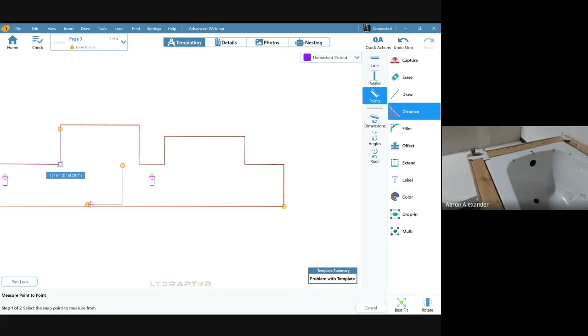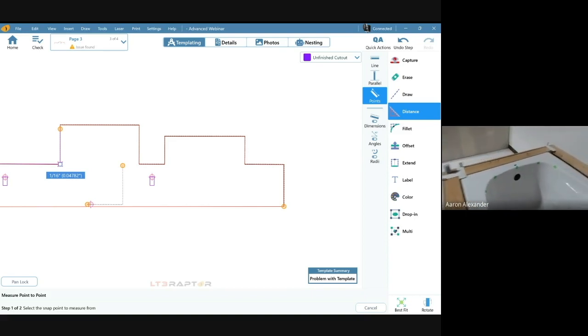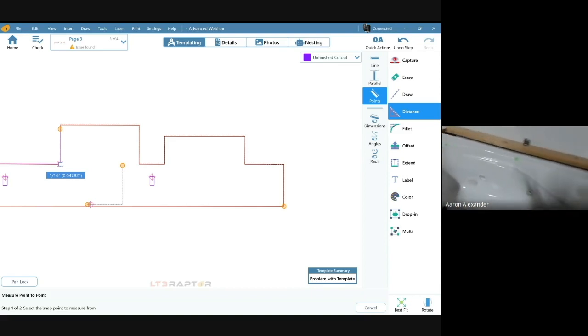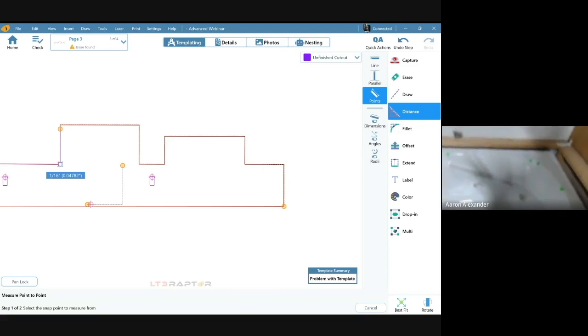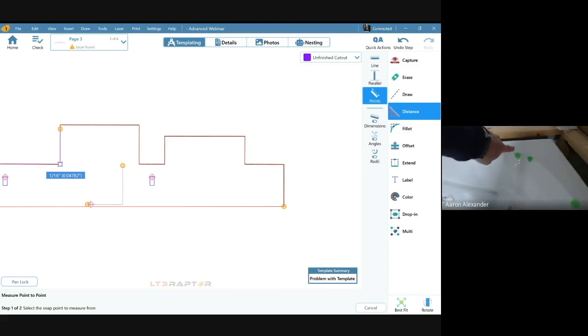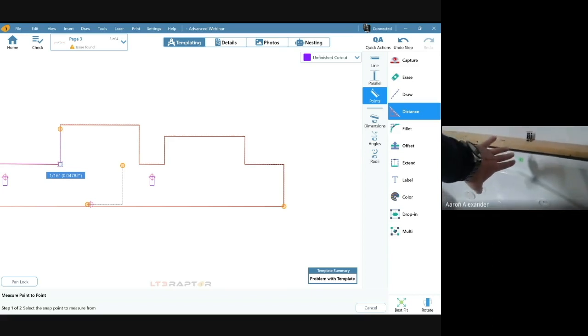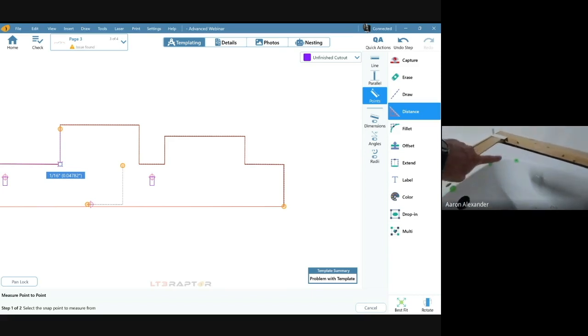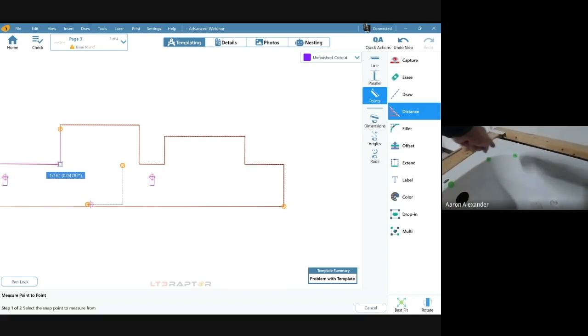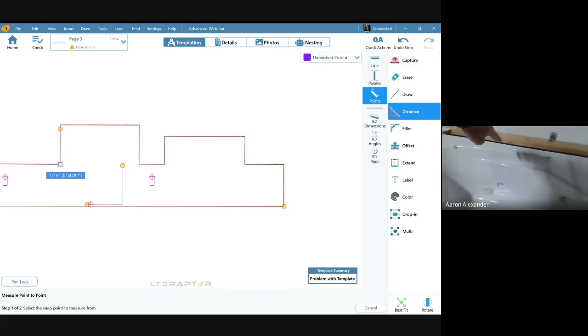One thing you'll notice here, I got my green sticky dots on our tub here. And you'll notice these pencil marks. On centers don't really matter as much. It's all about tangents. If you guys aren't familiar with what a tangent is, it's where this radius in that corner turns into this larger radius going across the back.